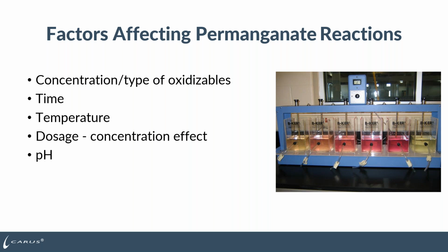So whether you do the jar test for 15 minutes, or you might do a jar where you do it for 15 minutes and then you come back in 30 minutes and an hour to see how much the demand increases over time. So are you still seeing a lot of reaction, or has the reaction really slowed down? The jar test takes into account temperature. Nothing changes because you've just got fresh water when you're doing it. And then you can keep track of pH and things that you're doing in the jar test.